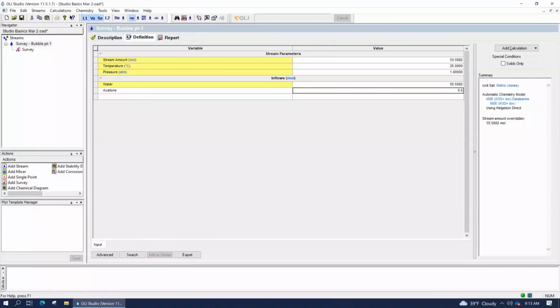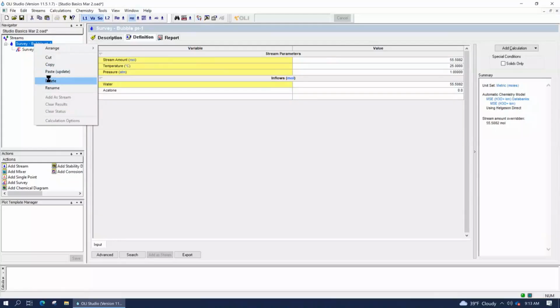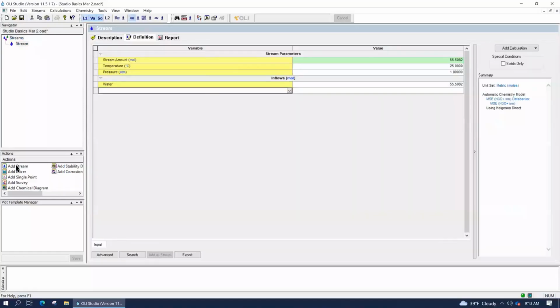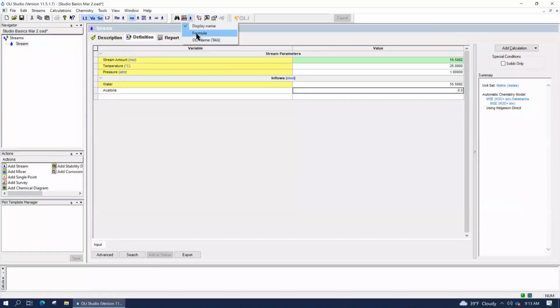Okay. So what I'd like you to do, in fact, I'm going to start from scratch again. So Faisal, you're with us, okay? Yeah. So make sure that you've got OLI Studio open, a new case file. I saved my file as Studio Basics March 2nd, and now we're going to add a new stream, just like we've done before. Always start with a new stream. And again, we're going to add acetone. Again, you show formula view, so I'm just going to go back to formula so you can see it.